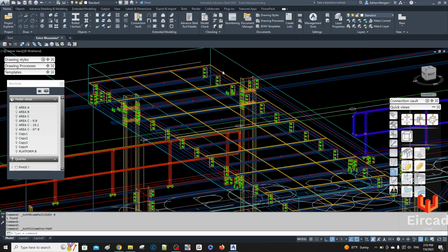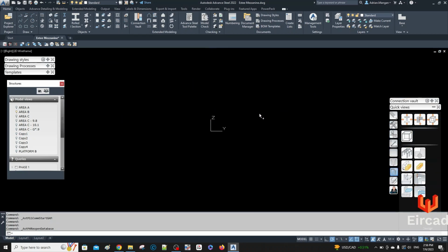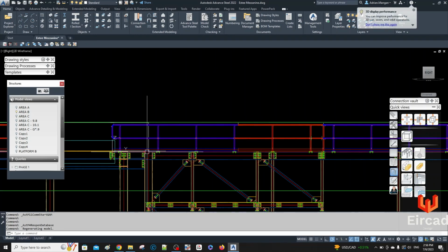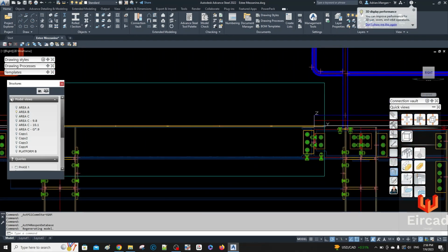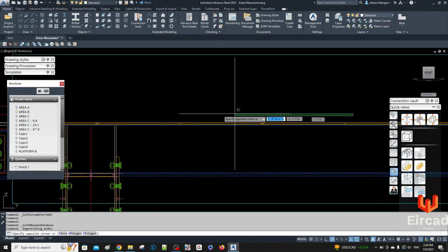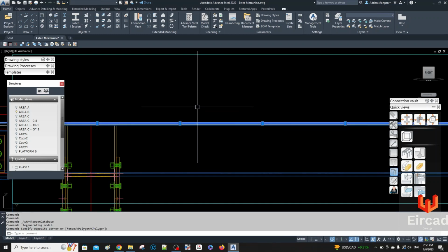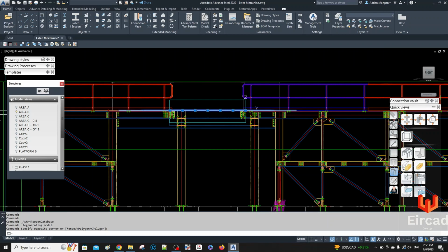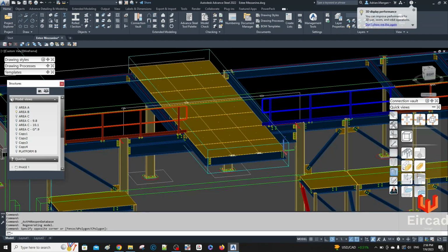So what I'm going to do is I'm going to update here. And then you want to pick all these plates. There's no model role with them yet, so model role is not really going to work to filter. So you can just come in here at an angle. So we can see this is our platform. You can see there's the break in the plate. So if we just come in here, that'll select all the plates, right? So now that should be all the plates.